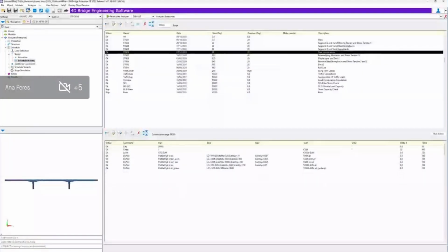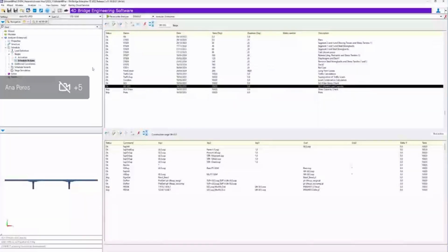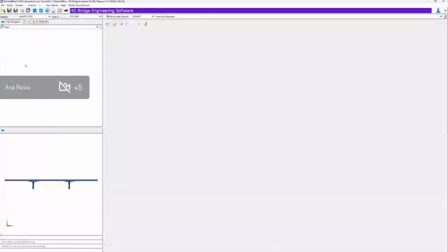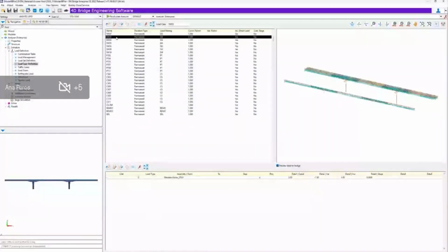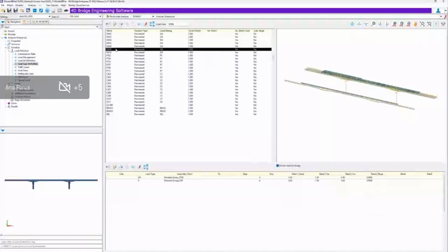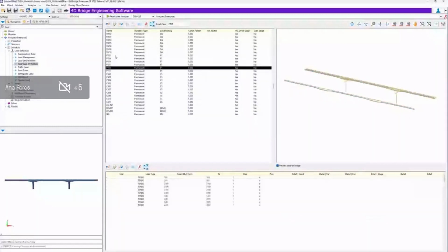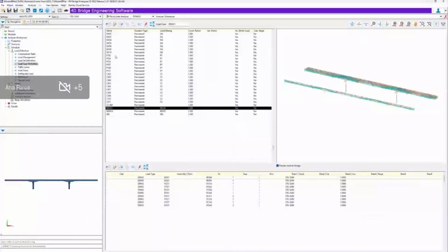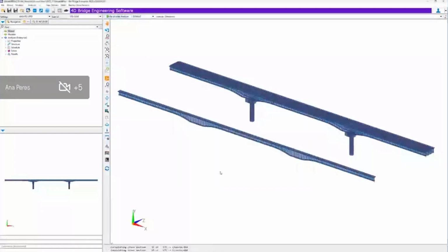So all the schedule actions are exactly the same that we presented before for one girder. The only thing that the user needs to do here is to introduce the deck elements on the load cases, in this case, for running simultaneously the two models, and to activate also the bridge deck elements in the stage activations. So we can now run.